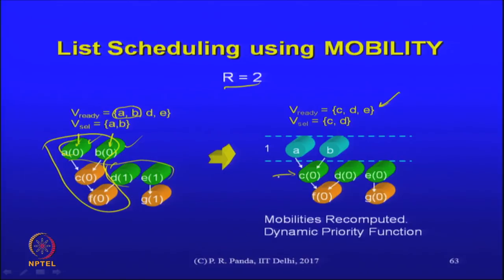Now when you run, you can see that all the nodes are on the critical path. In this simple example, there is actually no flexibility. If you run ASAP, you would assign all three of them to the first clock cycle. To the second, you would assign these. ALAP is no different. So, either way you need 2 cycles, no matter how many resources you had, because of the nature of the dependencies here between the nodes. You can see that all the nodes are on some critical path or the other of length 2. That is why all the mobility computations result in the same number.